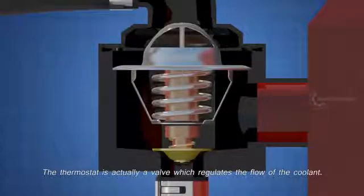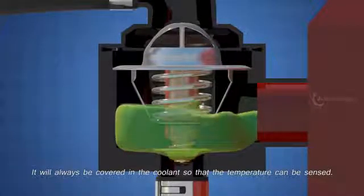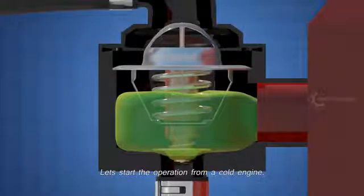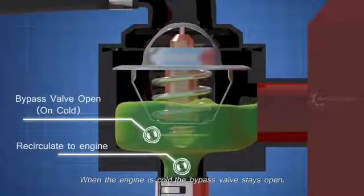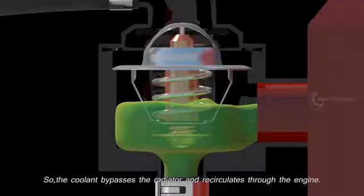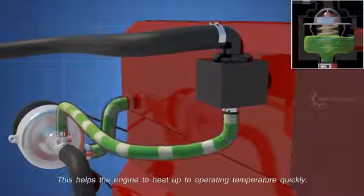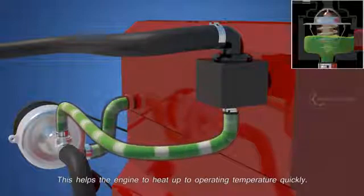So, finally, let's get into the working, starting with the thermostat. The thermostat is actually a valve, which regulates the flow of the coolant. It will always be covered in the coolant, so that the temperature can be sensed. Let's start the operation from a cold engine. When the engine is cold, the bypass valve stays open. So, the coolant bypasses the radiator and recirculates through the engine. This helps the engine to heat up to operating temperature quickly.